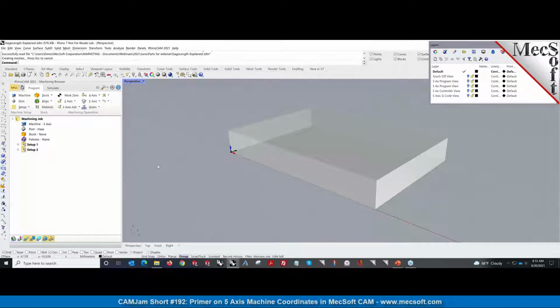If you do have the premium configuration, the machining browser is going to show up like that. And then you're going to have a 5-axis machining method drop down here. The different methods that we have available in 5-axis are curve projection. It's very similar to 3-axis curve projection, except that you can take a curve and project it in 5-axis mode, with surface normals acting to drive your machine tool angles.